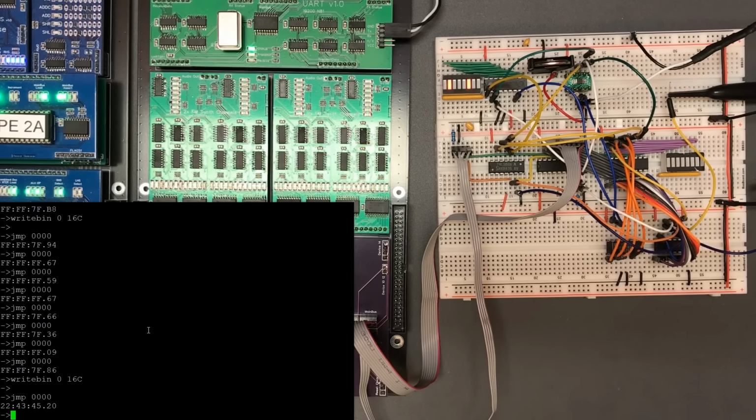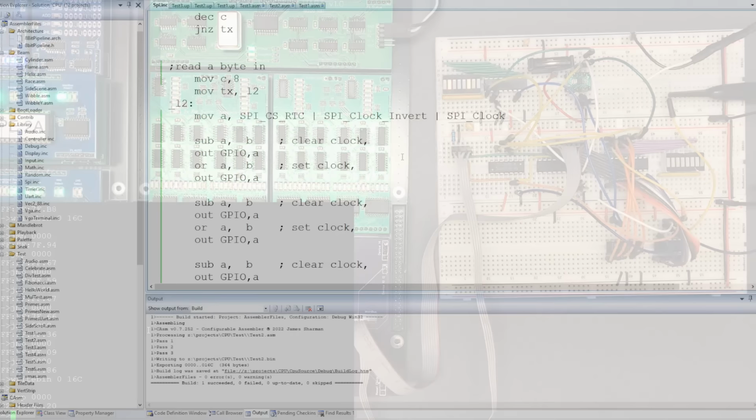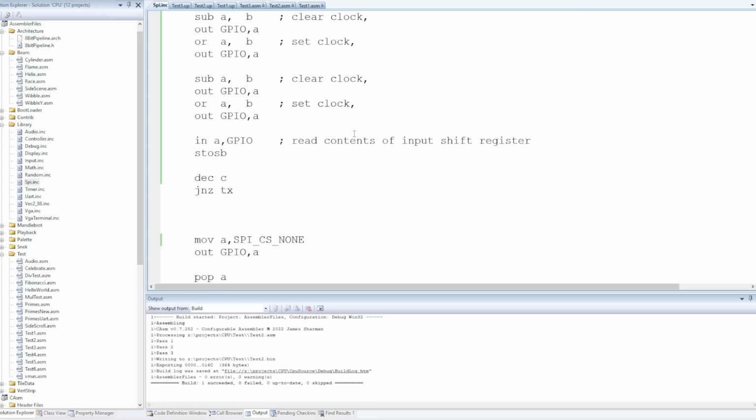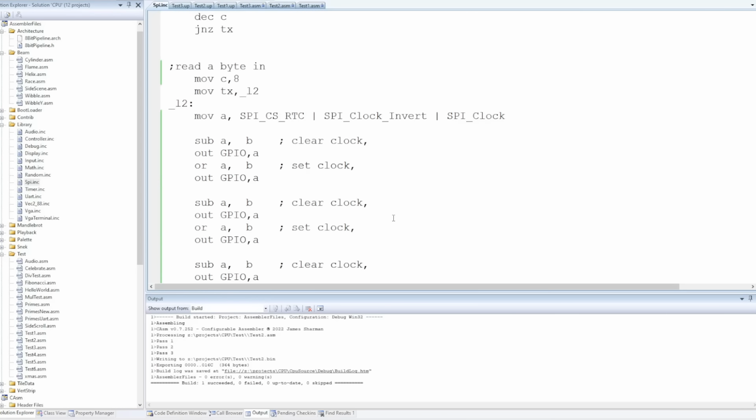Right, before we move on, let's take stock of what we've got. So now our loop is 2 cycles, 4 per bit. We read in once and store it, that's 3 cycles, then the same loop structure. So we have roughly doubled the speed of this by replacing 2 chips and adding 1. I'm pretty pleased with that.